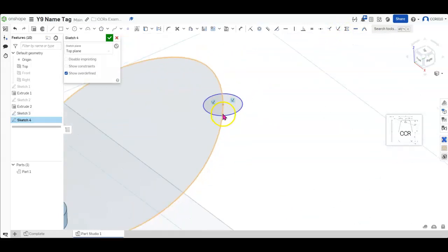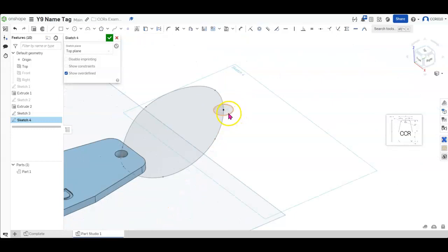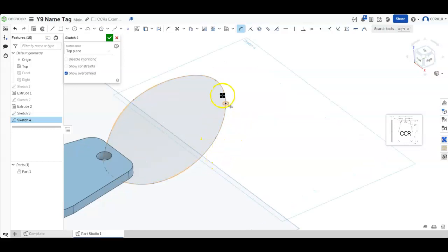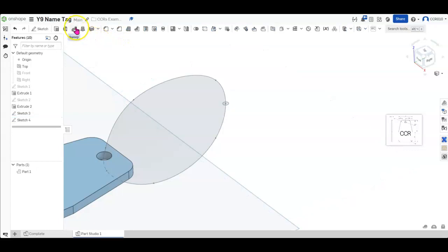That will move it so that it now pierces that sketch, i.e. they both line up. Let's make that sketch a little bit smaller, about 2 millimeters. So we'll select the dimension tool and turn that into a 2 millimeter diameter circle. So now we've got our profile sketch and our cross-section sketch. We can now come out of our sketch tool and use the sweep option.